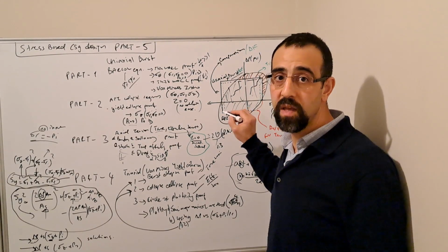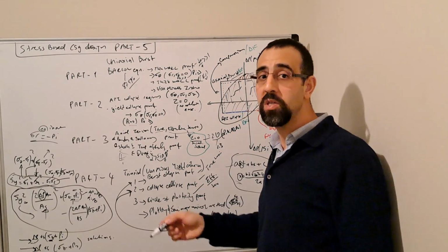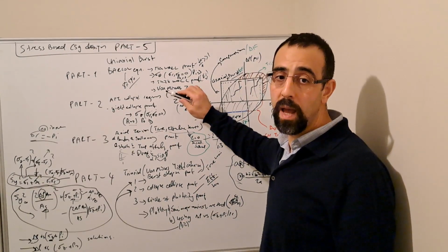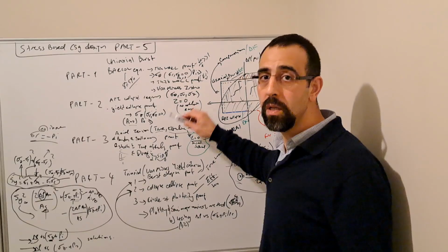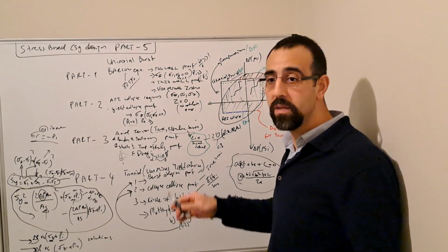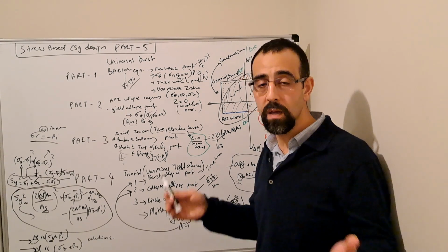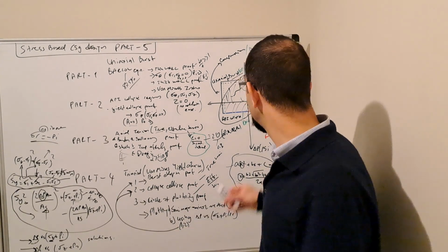And we said that it is different from the temperature derating on the yield strength, because we know that temperature has an effect on the yield strength. So if there is a derating on the yield strength, this can affect both burst rating and the collapse rating later on.